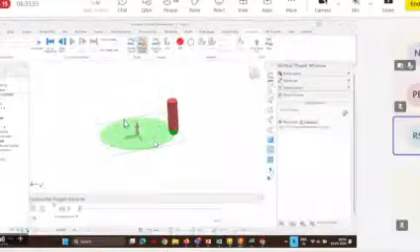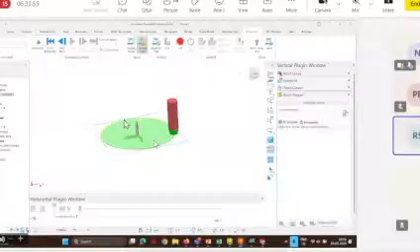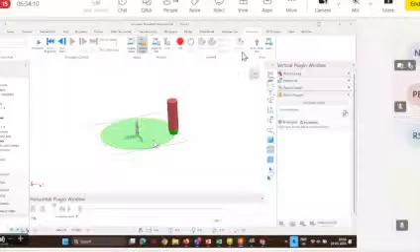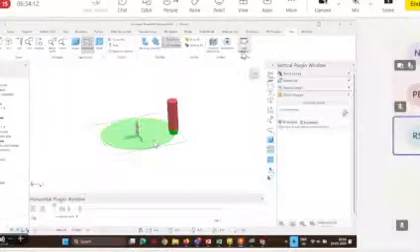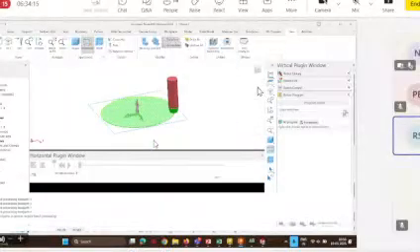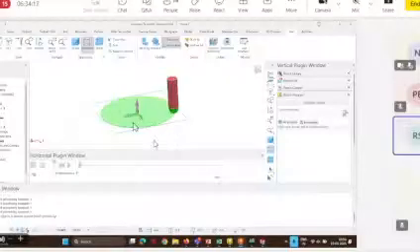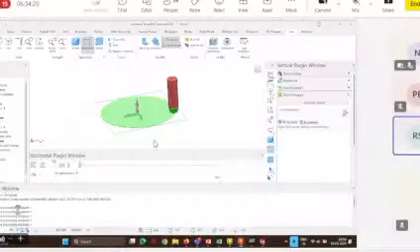Say suppose we want to record the commands for PowerMill also. Here also there are some examples. We can right click and start record, something like this. You can do it over here also. And if you want to see the command window, here also it's possible to see the command window. You can see whatever operation you have selected and done, the corresponding commands are already written over here.